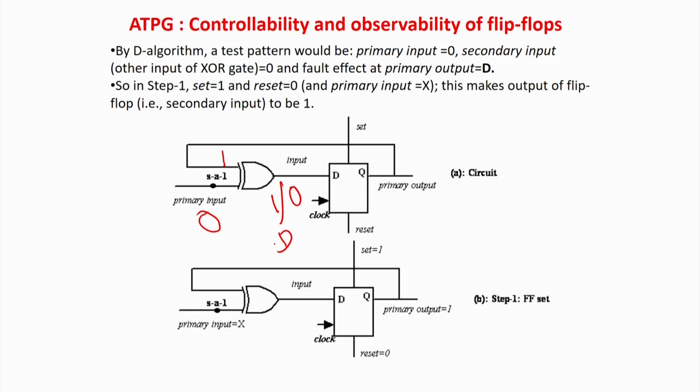So, something I require like this. So, this may be one test pattern. So, basically I sensitize and propagate the value through this, because there is only one output, the value has to be propagated to the input of the D flip flop. But actually the more important point here is to note that I require the value of 1 over here. But again, as I told you, directly you cannot control it, because it is a flip flop output.